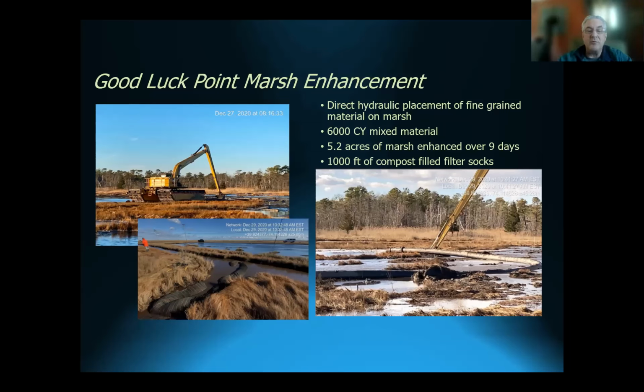We placed that material over 9 days on about 5.5 acres of the marsh. We used about 1,000 feet of compost-filled filter socks to block off the channels and to hold the fine grain material in, and to try to get some filling of those channels.